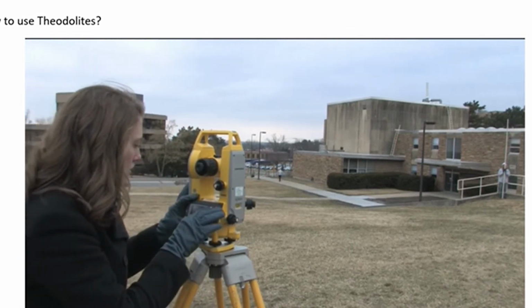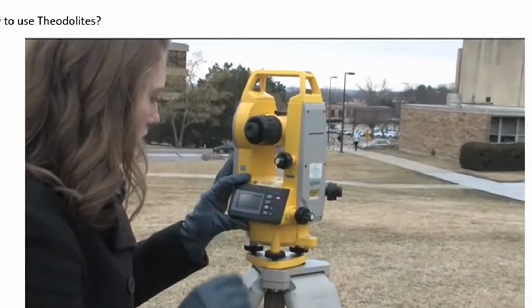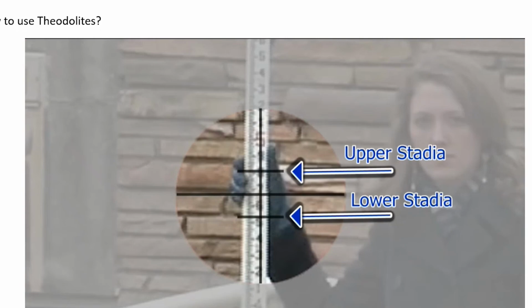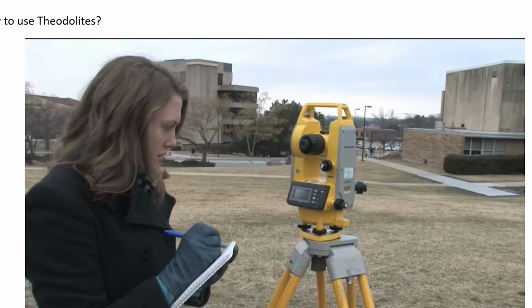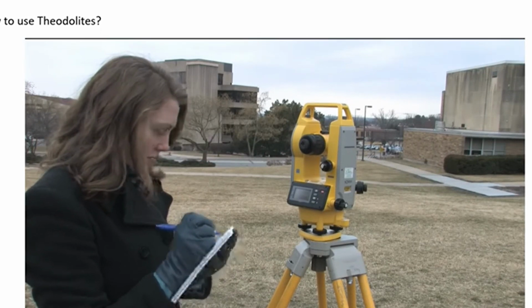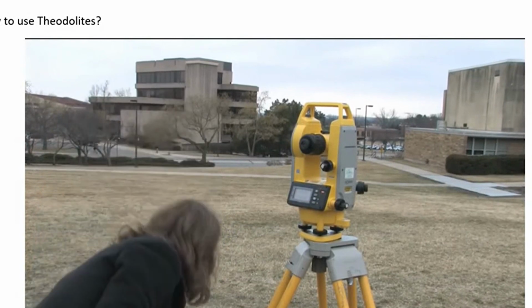Once the instrument has been carefully focused on the HI and the horizontal and vertical angles have been finely adjusted and locked, the operator will then press the zero set button on the instrument twice to zero out the horizontal angle. Next, the instrument operator looks through the scope and observes the upper and lower stadia readings and records those values into the field book. The upper stadia reading minus the lower stadia reading is your S value for point A. Also record the vertical angle shown on the instrument.